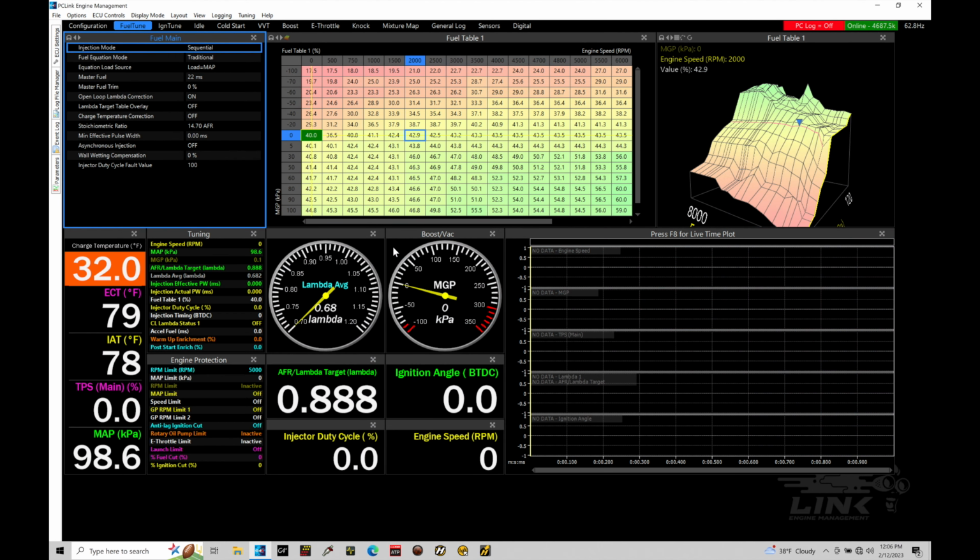Okay, so let's get started. We're going to be taking a look at setting up our output control using our Link G4x systems in our mini training tutorial. We're going to take a look at setting up two different types of output control. We have an on-off control and we have pulse width modulated abilities with our outputs using our G4x. We're going to take a first look at setting up a VTEC output to control a VTEC function on a Honda engine, and then we'll look at setting up a pulse width modulated output for boost control. And we'll talk about the differences as we're setting these up.